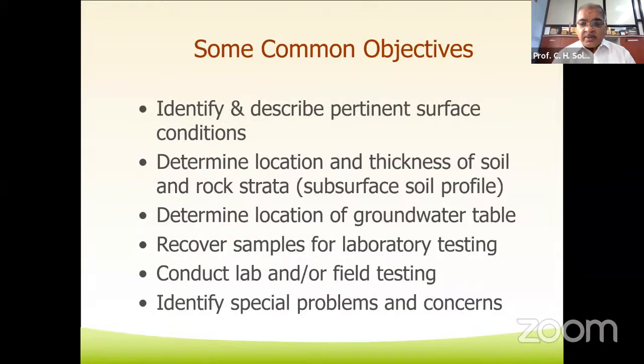Some common objectives of the soil investigation are pointed out here. One is to identify and describe the pertinent surface conditions. Second is to determine the location and thickness of the soil and rock strata. Third is to determine the location of the groundwater table. Fourth, recover the samples for laboratory testing, conduct the laboratory and field testing, and identify the special problems and concerns.